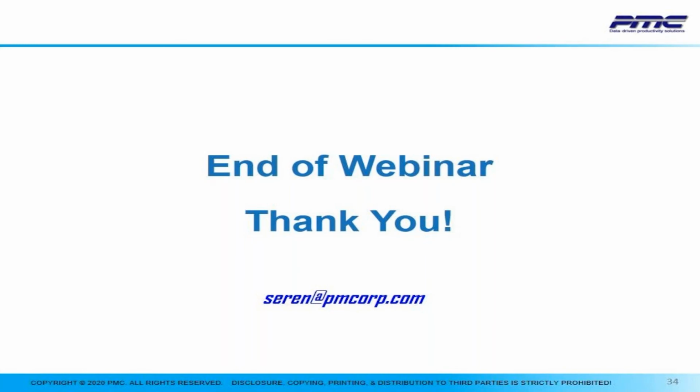For each failure mode, you must consider those 4 potential customers. We need to list all the effects on each customer type, but then to take it further in the risk assessment, we need to take the most significant effect, so that way we're not overanalyzing, which is one of the common mistakes that people make.